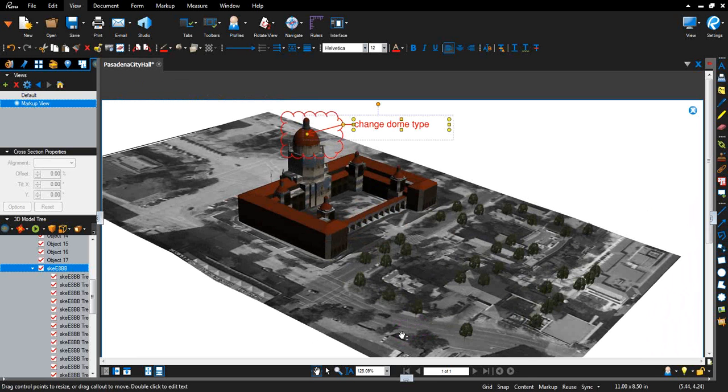So especially when it comes to Navisworks and stuff like that, if you've got a clash that's been detected, export it to PDF, then you can mark it up all you want, tell everybody what they need to do to fix the clash, send it on out. That could even be sent to the owner who doesn't have any software to view the Navisworks 3D models, but does have a PDF viewer, because 3D PDF is part of the PDF ISO standard.